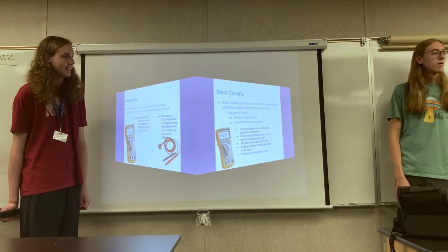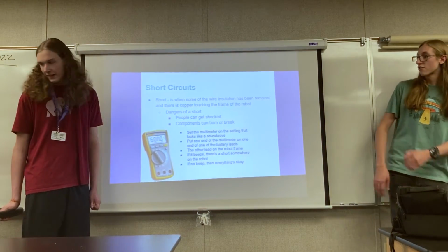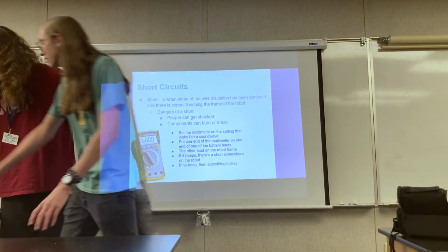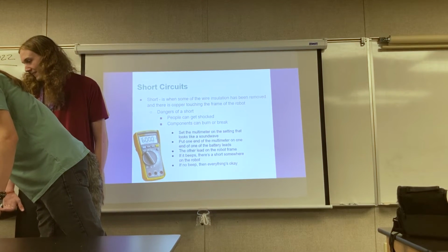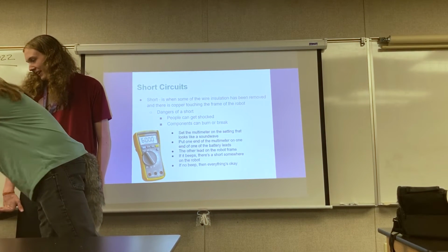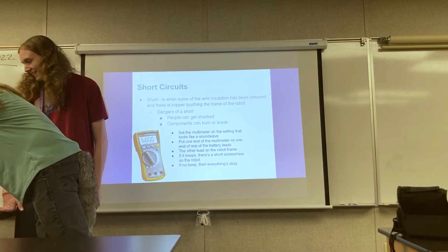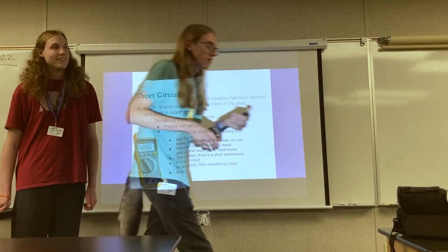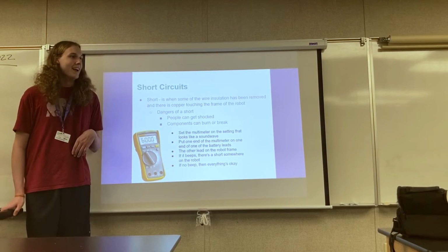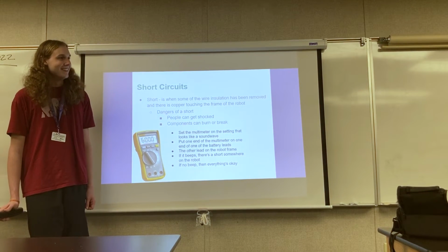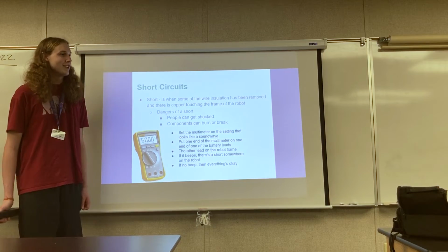We make use of fuses. Yes, actually. We have fuses all on our PDP. These are all 40 amp fuses. I'm going to pass this around, but this is a 40 amp fuse, and if that pops, we definitely did something wrong. It shouldn't get to 40 amps.